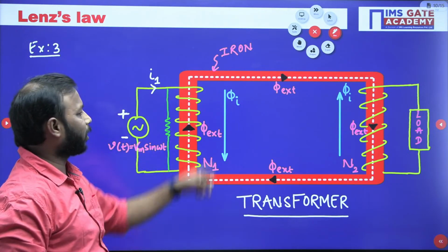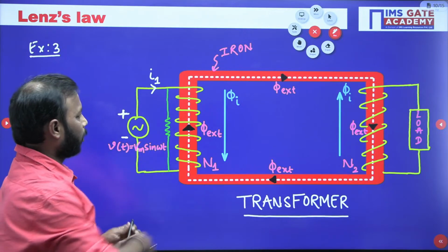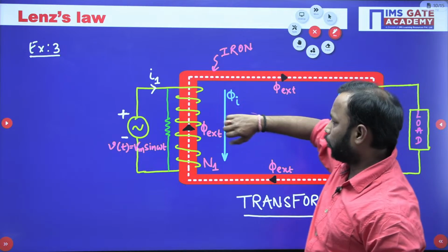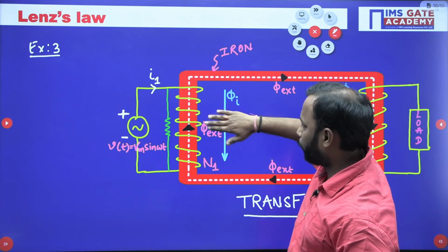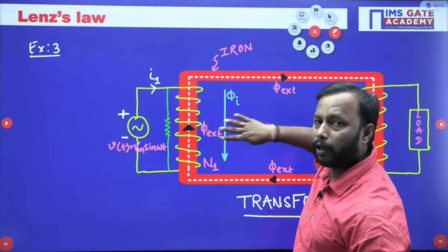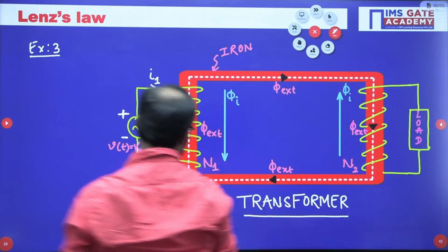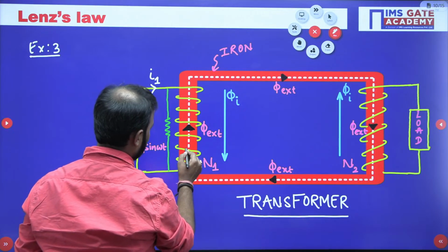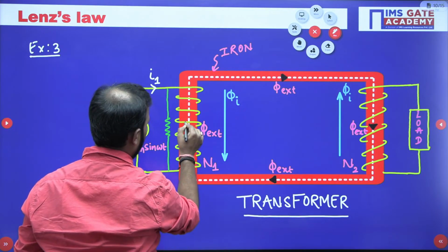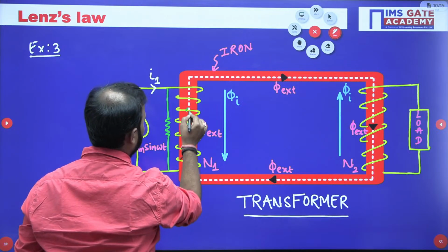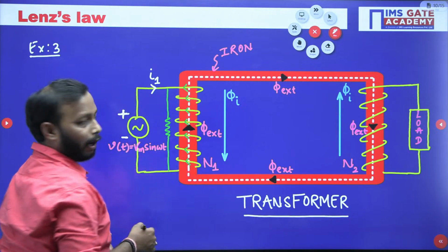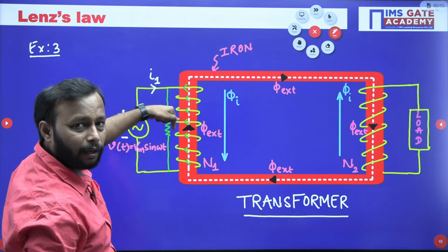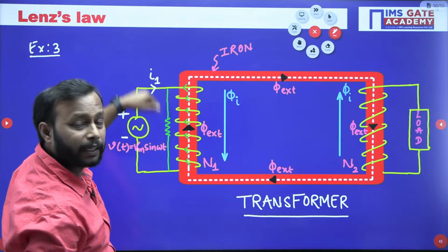Then what is the direction of the induced current which is flowing here? So see, phi induced is downward, therefore the induced current direction should be, from the front side, from right to left. So like this. Then this current is going to enter here. So this part will be plus, this is the fictitious resistance, na?